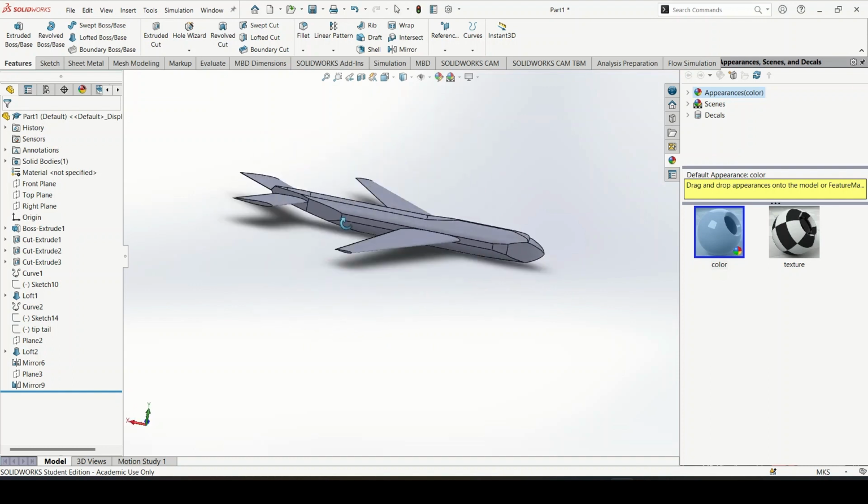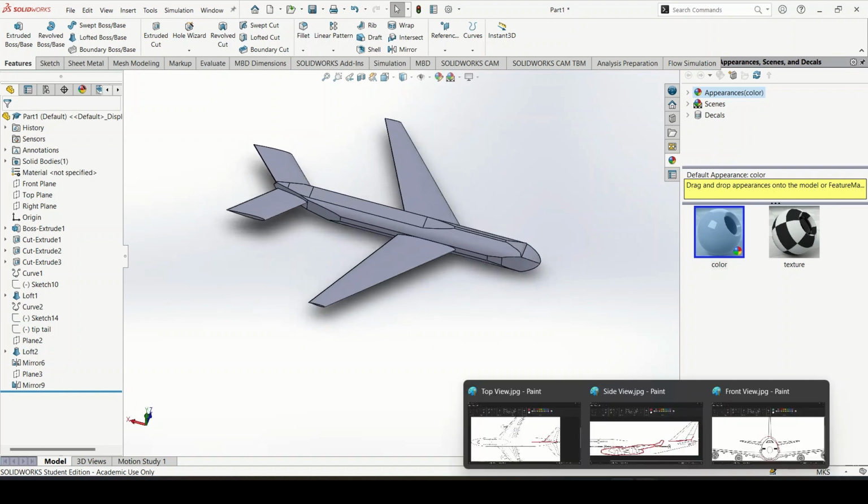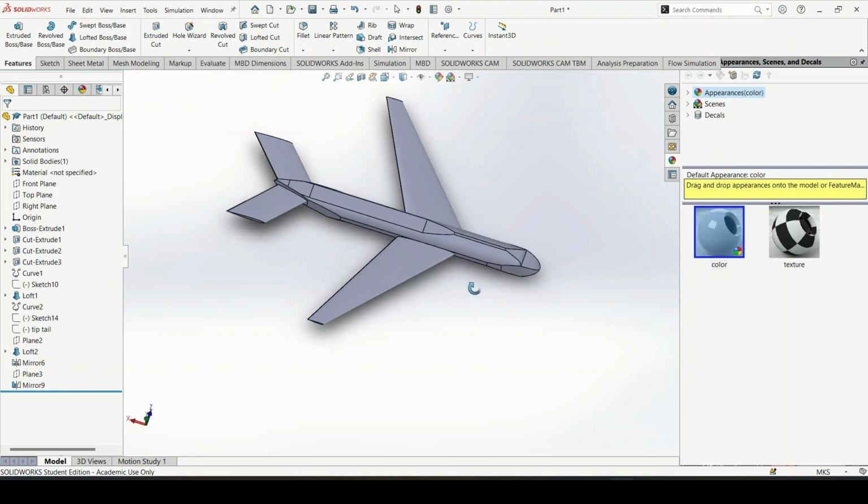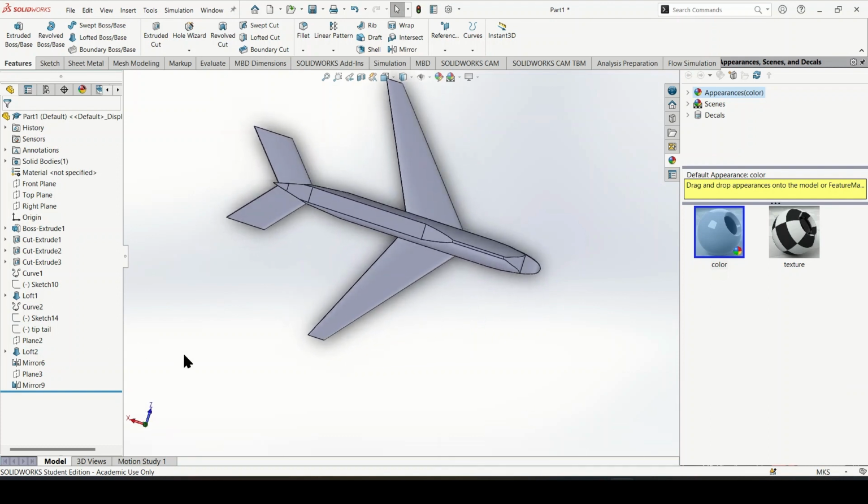And now we can create the vertical stabilizer. However, we will want to adjust the plane the airfoil is created into the XZ plane, meaning the Y will now have all the 0 values.